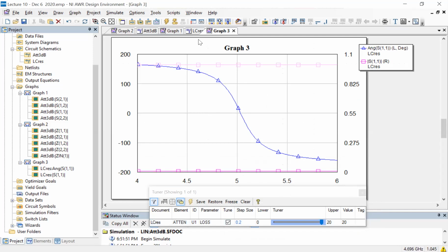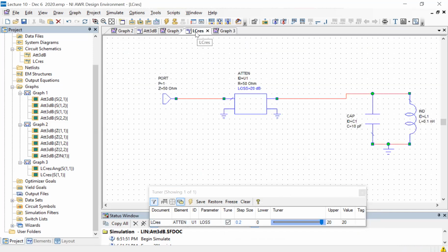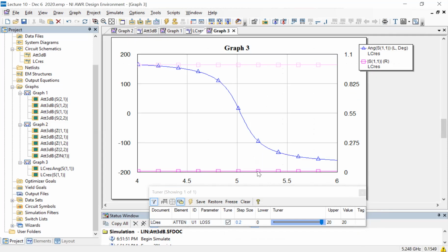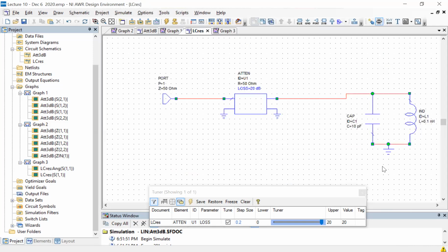And how do you even interpret this reflection coefficient? Because the reflection coefficient magnitude looks like 0. So from the point of view of interpreting the reflection coefficient as an equivalent termination impedance, you will say, oh, this looks like a perfectly matched load because very little power is coming out. So you will not even think that there's actually a resonator there.